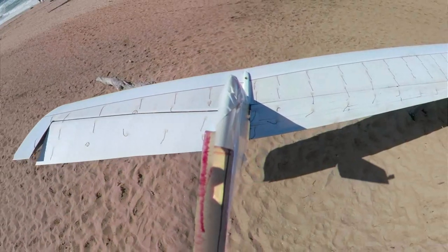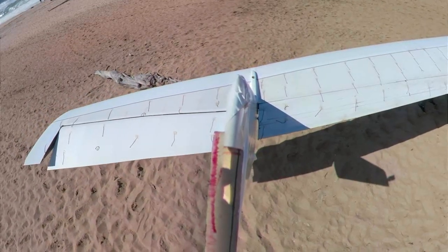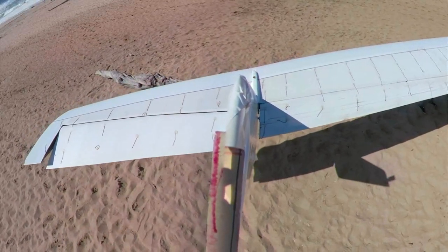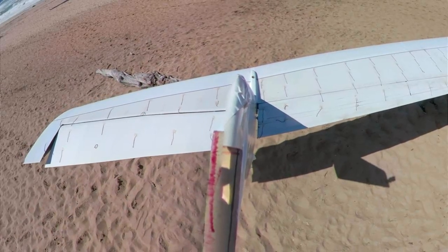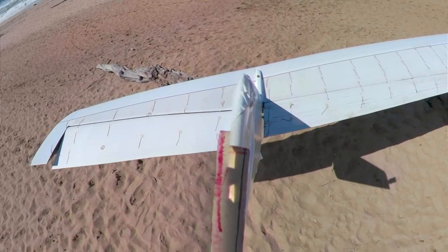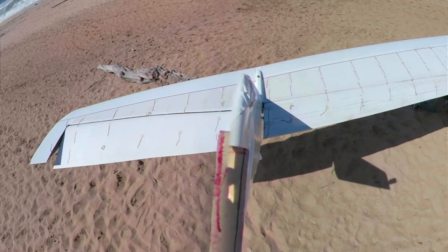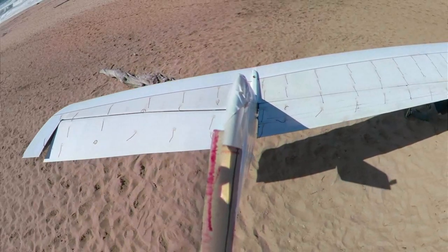We have incompressible flow. We can't have a vacuum in there. Can't compress it, can't have a vacuum. So the other flow just goes to fill that vacuum, and you're dragging the flow off the wing span-wise. So if the tip is messed up, you're going to mess up inboard, and you're going to have a nasty time trying to control the aircraft.